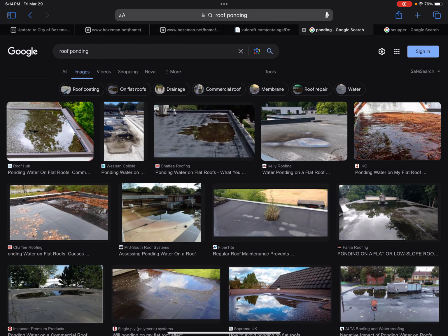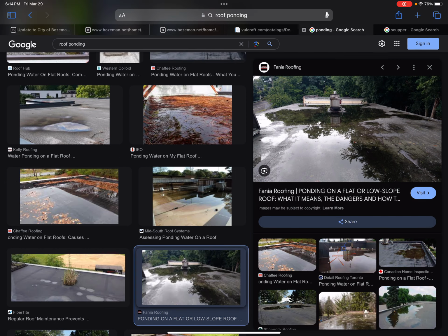but if we go back here, this is a typical TPO, or they call it an EPDM roof. Essentially, it's a rubber. All of the joints are sealed with basically like an asphalt or liquid kind of rubber cement, if you will. And then all these layers of rubber are interconnected. And underneath this rubber, on top of our metal deck or roofing structure, they lay down insulation. And that insulation is then laid down in such a way that it slopes to drains within the roof system.